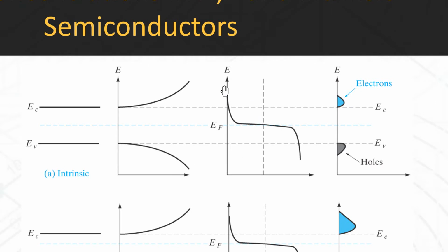The Fermi function looks like this. It drops to 0 above Ef and goes to 1 below Ef. The purpose of these plots is so you can visually see what happens when you multiply these two functions together. The density of states is 0 within the band gap, but it increases as you go to higher energies, while the Fermi function drops as you go to higher energies. To get the electron concentration, you multiply those two together.